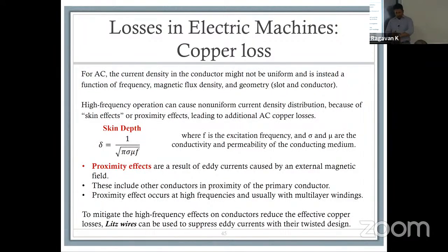Okay, so in terms of losses in copper losses, you can define the idea in terms of skin depth and proximity effect. The ideas are simple. Skin depth. Have you all come across the term skin depth for high frequency components? Skin depth really is the amount of your conductor where your current flows, right? The higher the frequency, the smaller that area is going to be.